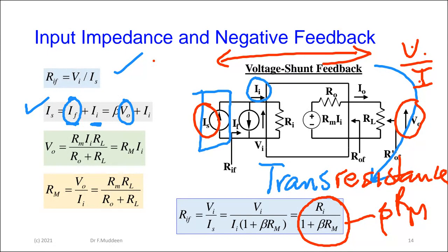When you review it, of course, you have the slides and you have the recording, but just conceptually, what I'm saying makes sense? You can see it. And again, just remember, if you're trying to figure it out, if you're feeding back voltage, voltage is going to subtract from the source voltage or the signal voltage. So if you lower the voltage, it means that the current going into the device is going to be less. In other words, as far as the source is concerned, the resistance to current has increased.